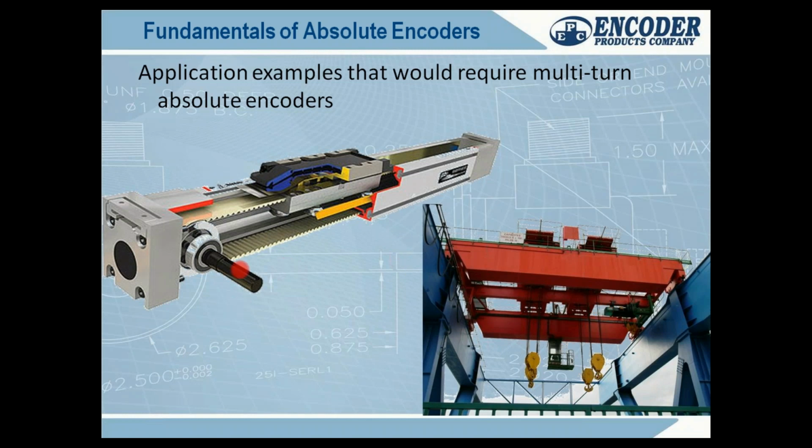This is a table, same idea, that if we have a servo motor with an encoder on it, that encoder is giving a position, and that motor is going to drive this shaft more than one revolution. It's going to be multiple revolutions to move this table from one end to the other. So we need to know the number of turns plus its position in a circle to know the location of this table.